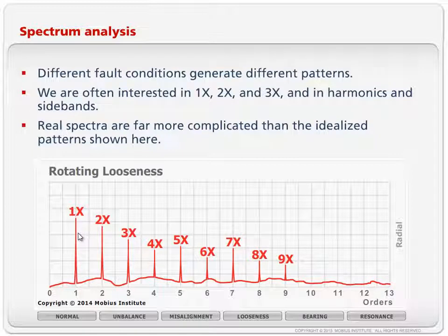When there is impacting going on or the vibration is just sort of distorted, hard to summarize very quickly, instead of just one peak, we'll see 2, 3, 4, 5, and they may all be a similar amplitude. In fact, they might go up in amplitude or they'll go down. And we sometimes see the noise floor, the bottom of the graph, lift up as well. So, lots of different patterns.